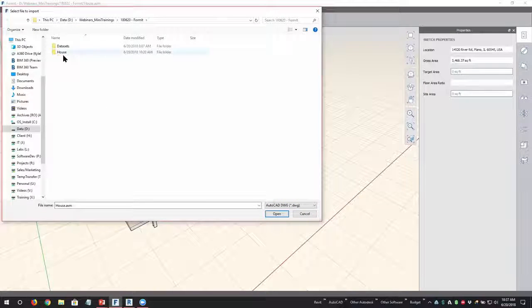So you can bring in your DWG if it is a Civil file. I think you would have to export to AutoCAD from Civil, so that it's just an AutoCAD-based DWG instead of a Civil-based DWG. I know Revit prefers an exported DWG as well, so Format would be pretty similar, so that when you transfer these back and forth, you have that there.